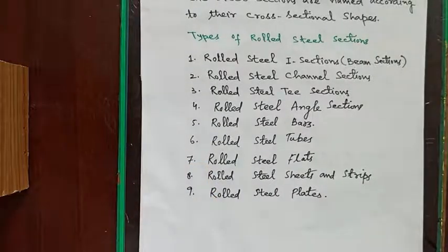The majority of structural steel that is used as building material is hot rolled structural steel. The process of hot rolling involves rolling steel at a temperature above the recrystallization temperature of steel, which takes place at over 927 degrees Celsius. Steel that is above the recrystallization temperature can be shaped and formed much more easily than colder steel without any loss in ductility.